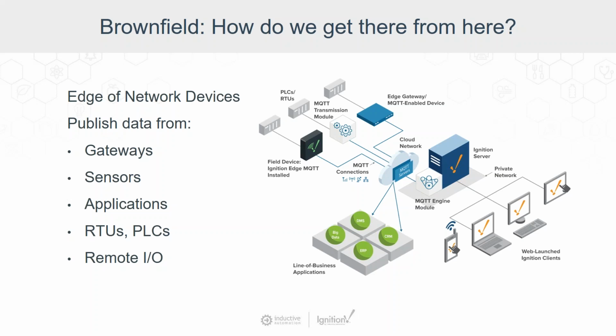And again, in the brownfield world, that's the world we live in. How do we get to this new architecture from there? And that is where we can deploy the Moxa hardware with Ignition Edge. We talked about that earlier. Ignition Edge is a software that would run on that equipment that has drivers to PLCs, or Allen Bradley, Modbus, Siemens, Opto 22, SnapPAC, DNP3, and more, and can bring that information and do that protocol conversion, publish it to an MQTT server.